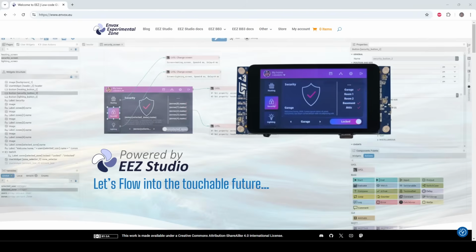To test the LVGL implementation, we could either simply create our own hand-coded elements that we then display for our display and pass to LVGL, but my preferred method is simply using a drag-and-drop editor. Now, there aren't terribly many available. There used to be one called Squareline Studio, but I think the support for that has now stopped. So I found this other one by Envox, which is called EEZ Studio, which is free and very quickly lets you test user interfaces for LVGL and design them as well.